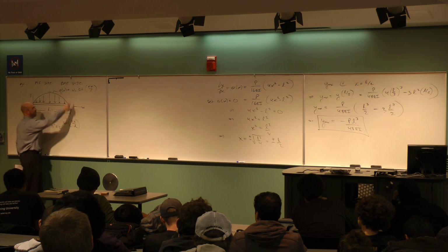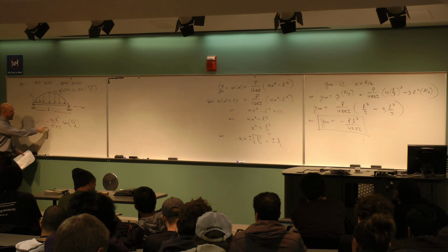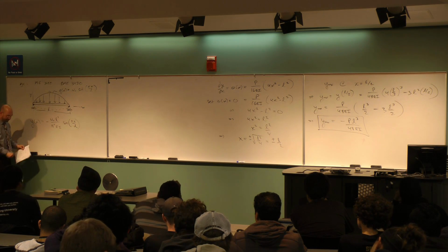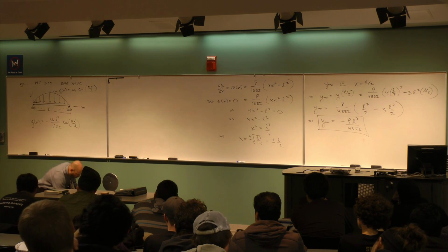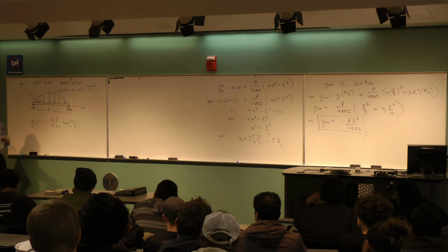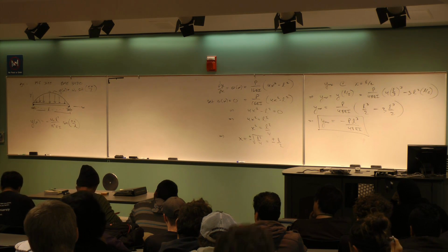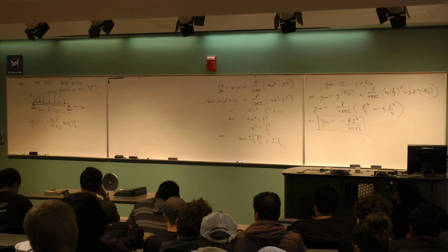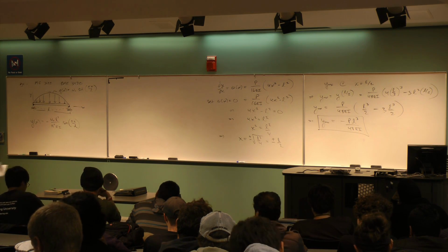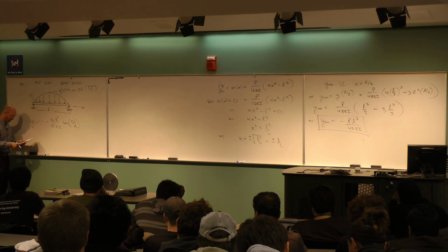Length. This has units of force per unit length. The behavior is affected by the E and the I and the L, right? So that's all in there. All right, great. So what I'd like to do is just illustrate how all these derivative relationships work. I wrote this all on the board last time: the first derivative is a slope, the second derivative with an EI gives me a bending moment, then the third derivative is a shear force. Let's see whether or not those things all work out.